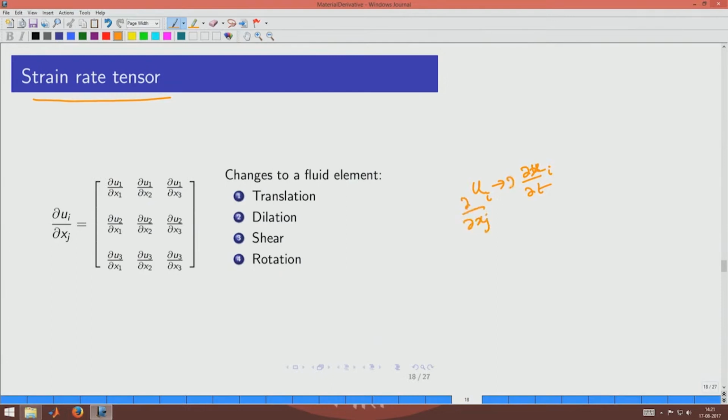Okay, so which means that when you combine these, this is like strain, the change in length by length, and this is giving you the rate. So this is nothing but strain rate, and the units are just second inverse. If it has two subscripts, you can guess that it could be a second order tensor, which is true, and one can also prove it.